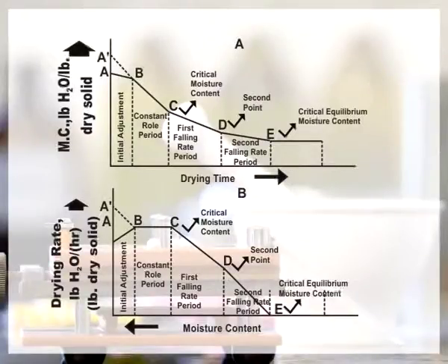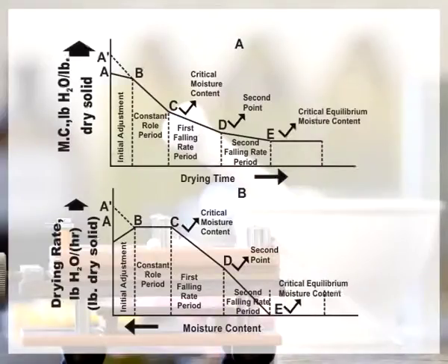In this period, the rate of diffusion equals the rate of evaporation. The diffusion of water from the bulk and the diffusion of water vapor from the surface to the environment are equal. As drying proceeds, the coarse capillaries are completely depleted of water and the solid falls through the maintained uniform film. The area over which the moisture film is not present is known as the dry spots.